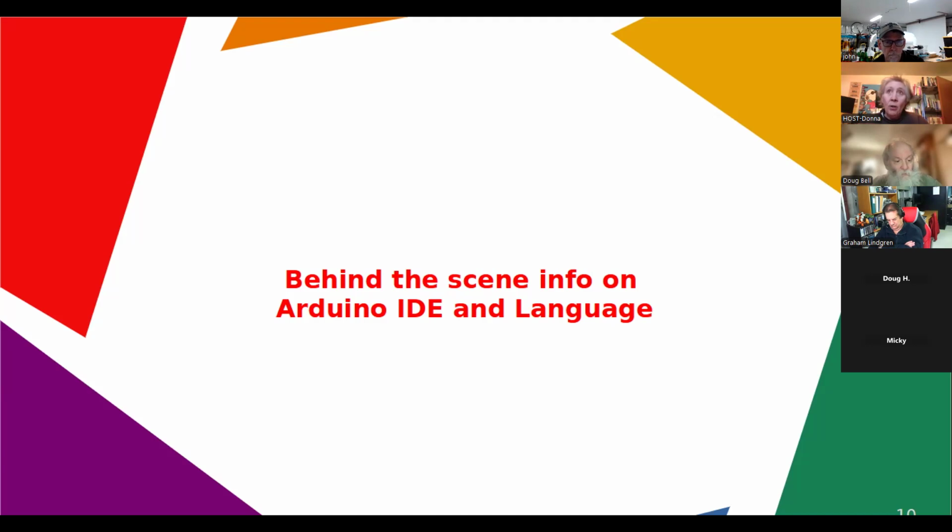And the Arduino variant of that is called the AVR, because the lower generation or minimal functionality Arduino boards are all based on Atmel AVR processors. Therefore, the Arduino port of GCC is called the AVR port of GCC. And that contains the compiler, the assembler, the preprocessor, and the tools needed to convert object code into a single binary, which ultimately gets downloaded onto the board.